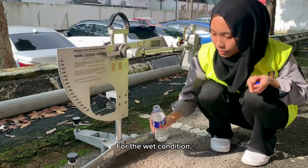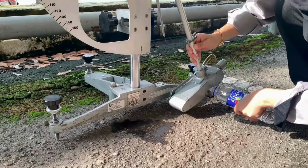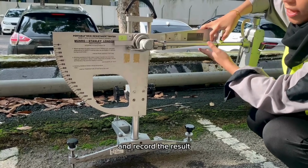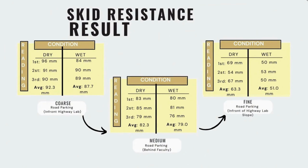For the wet condition, wet the test area and wet the rubber slider before the test. Next, make 3 more swings and record the result. Finally, repeat the same steps for 2 different locations. The results are shown for the skid resistance test.